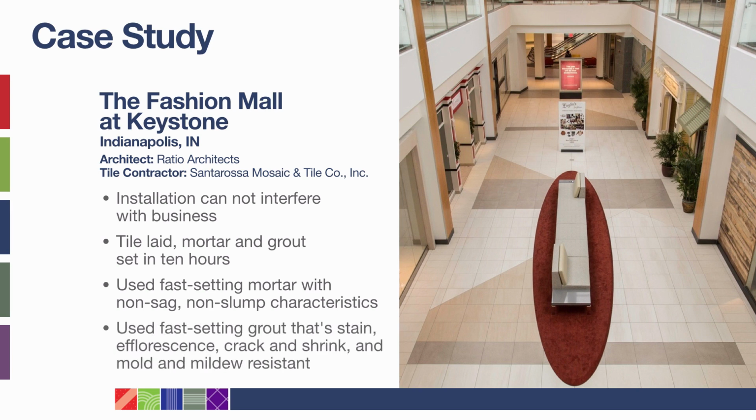They used a grout to provide the high stain resistance critical for commercial environments. The grout also had fast setting capabilities and provided color consistency, efflorescence resistance, crack and shrink resistance, and mold and mildew resistance. It exceeded ANSI A118.7 specifications. This project illustrates that if proper guidelines are followed, large format tile can be installed quickly and efficiently to create